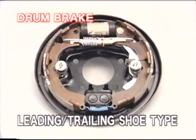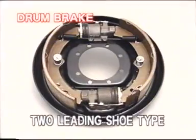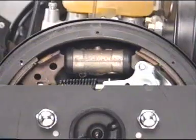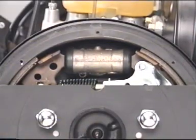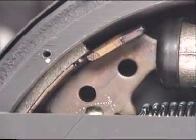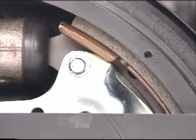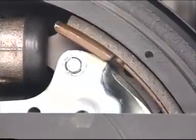Types of drum brakes depend on shoe installation or number of cylinders. For example, the leading trailing shoe type, 2 leading shoe type, and duo servo shoe type. The hydraulic pressure transmitted to the wheel cylinder forces the shoes apart. The lining installed outside the shoe rubs against the drum, revolving with the wheel, and produces brake force.